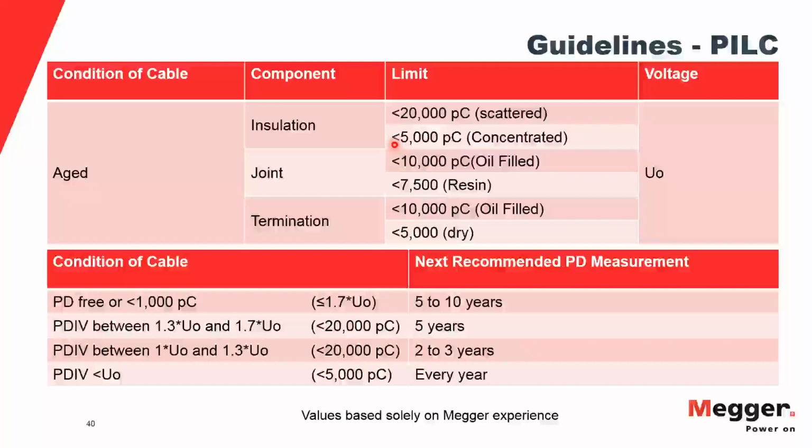Next question is for Jason. Here, VLF Sine wave test is not showing PD, but it is showing in other waveforms like CR and DAC. How do you cope with this? Also, are background noises too sensitive to detect PD emission?